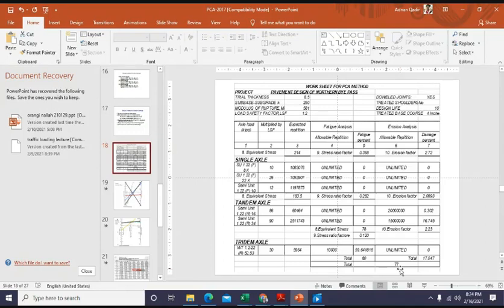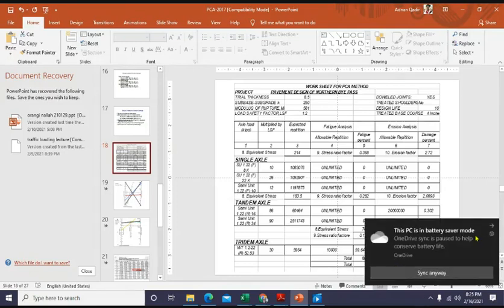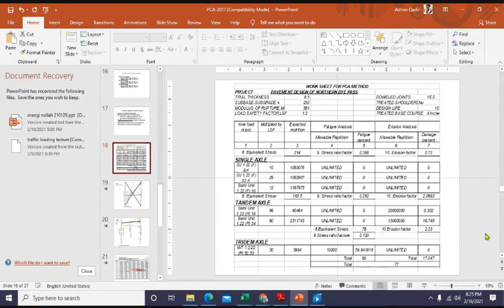And you can say, okay, this may be my final thickness. But mind you, for economical reasons, we may go for another trial. If we reduce our thickness to say 7.5, and for 7.5 the total becomes more than 100, then I see that my value is not acceptable. If it becomes 7.5 and this total becomes 99%, that's my final thickness.